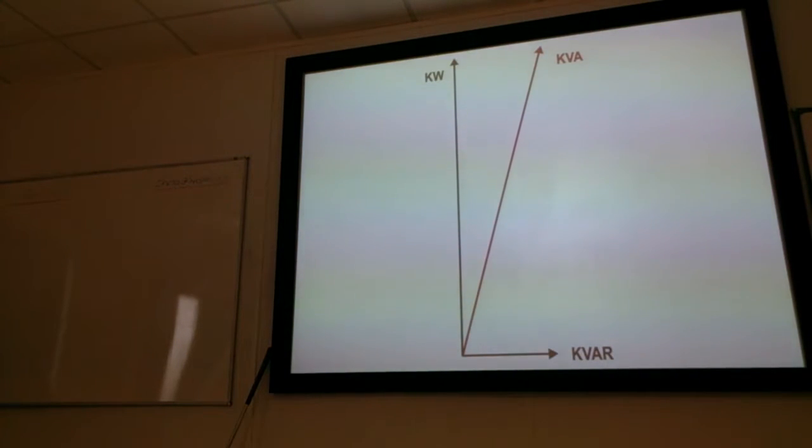You'll also hear the terms kW, kVA and kVAR. Kilowatts is the real, true, active, effective or useful power. It's the actual power we can use from that system. kVAR is the reactive or wattless power. And kVA is the total apparent power. That's what it looks like we've got, but that's not all we're actually going to get out of it.